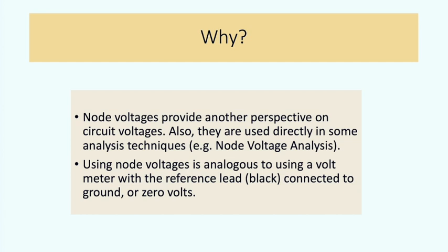Ground is assumed to be at 0 volts. So we take our red lead and poke around in a circuit making measurements. All of those measurements are with respect to ground, and those are node voltages. So they're encountered commonly in practice.